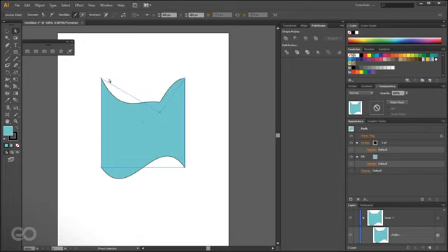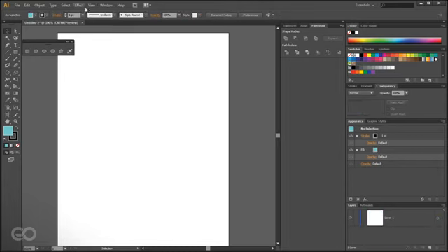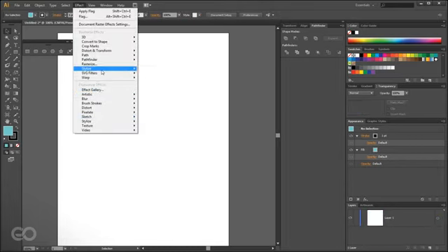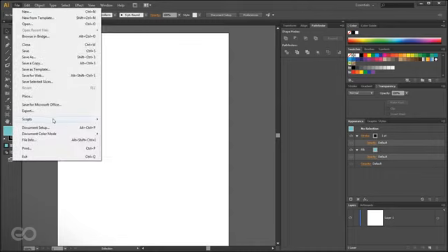So it basically means this rectangle which is skewed is the one which is actually being waved about. It's quite a useful effect. So that was the warp flag. Like this, you have several effects. You can go through them, look at whatever you want at that particular time and use them. Apart from this, if you go online and search for Illustrator scripts, there are several scripts that people have created which you can load in using the other script options over here, and you can pretty much get any kind of effect you want inside there.